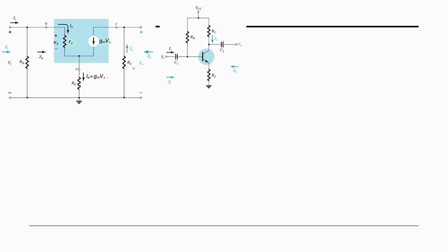If you look at this structure, our R pi is actually not in series with our RE. Why? If you look at the junction here, the current is split. One goes to the emitter, and another current coming from the collector also goes to this emitter. So R pi and RE are not in series. In this case, we need to introduce something which we call VT.